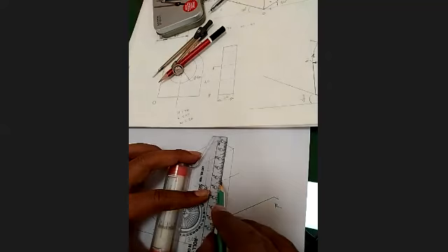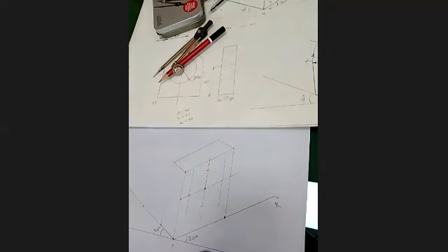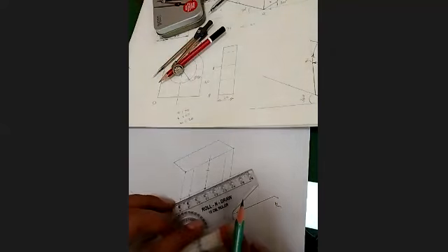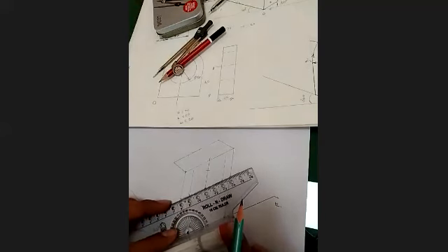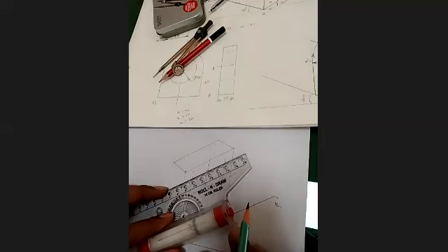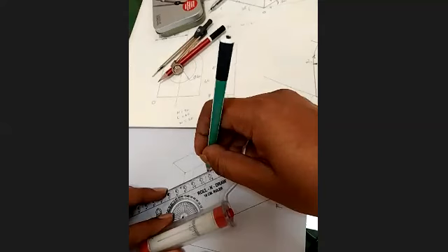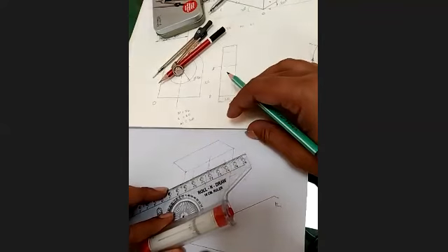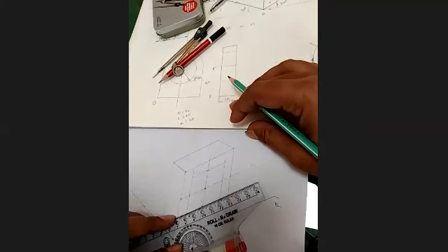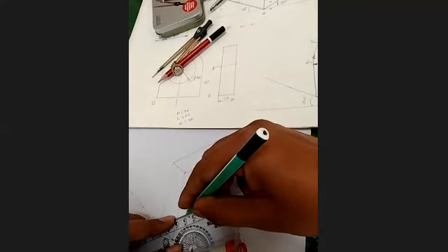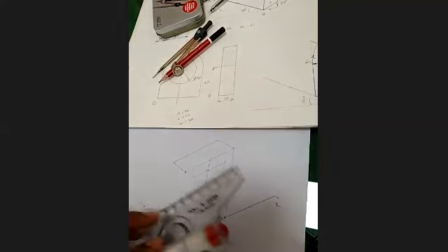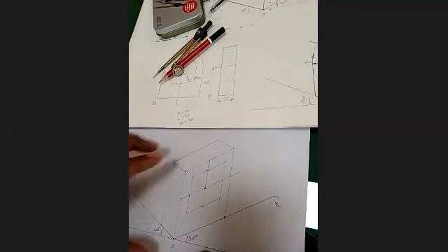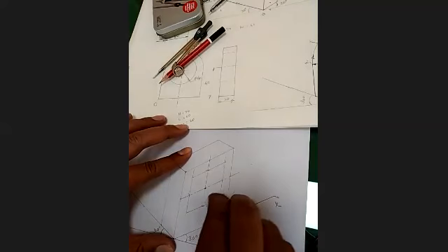Similarly, from another center on horizontal center line, you should get the line. Then you align this roller scale edge with the horizontal center line and get the line passing through the arcs which is cutting the vertical center line. Through that point, you should get the line. Similarly, move the roller scale and get the bottom. And it will give the rhombus.